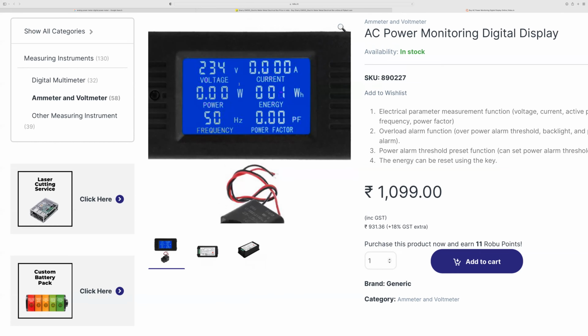so your meter itself, if you have a digital meter at your house, you can actually have a look at it. One is you can see the voltage, you can see the amount of current that is being drawn by the devices put together. And last one, that power factor. That is the cos phi that I'm trying to talk about. And generally, that power factor will be a value varying between 0 and 1. It has a significance. And how that power factor is calculated is purely dependent on what kind of electrical devices we use at our home.